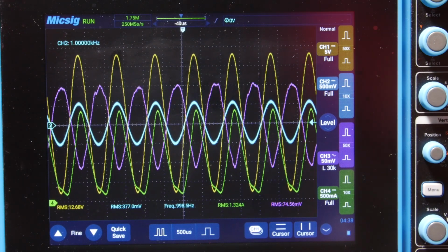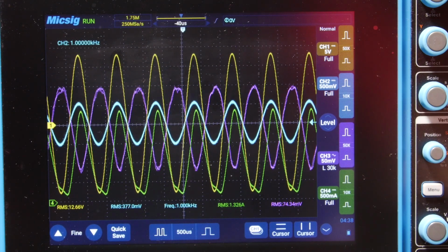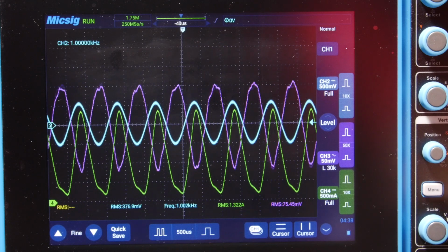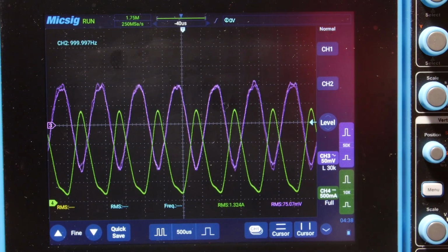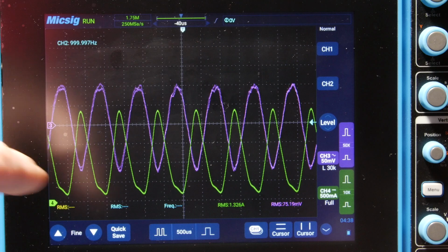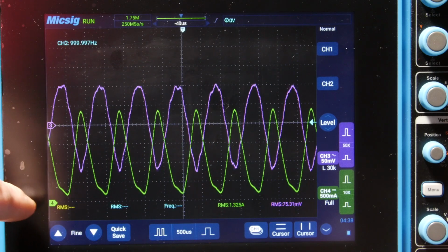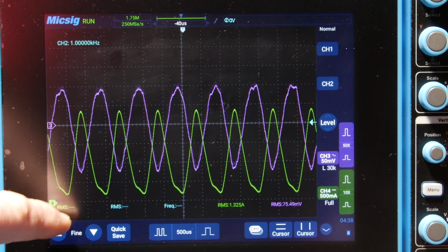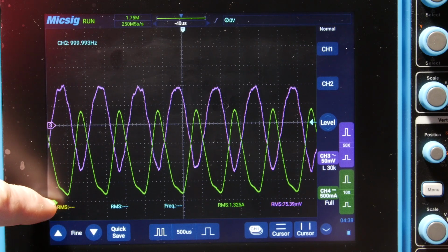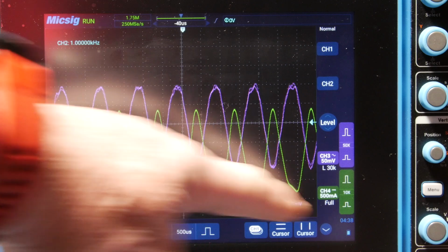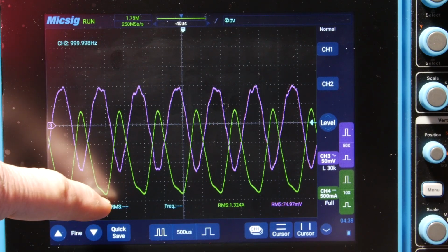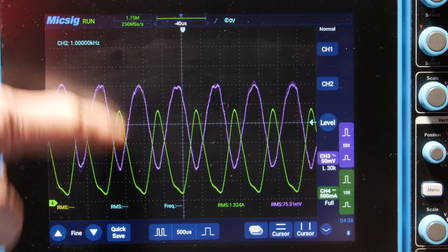Okay, now let me turn on the current. Okay, now that's the current. I'll turn off the voltage, output, input just for a moment. Okay, so that's the ripple on the power supply, the lab power supply coming in, the plus rail, and see how we're just coming off of the, what is this, 500 milliamps, so it almost comes down to about 250 milliamps.